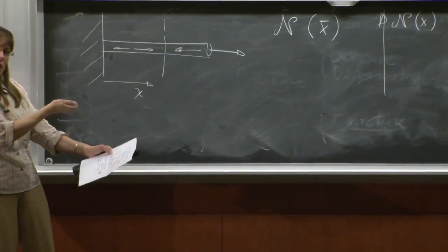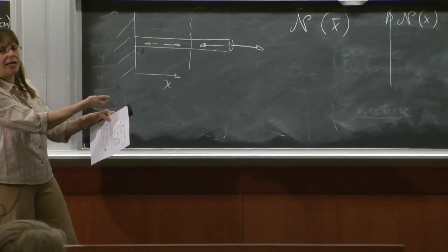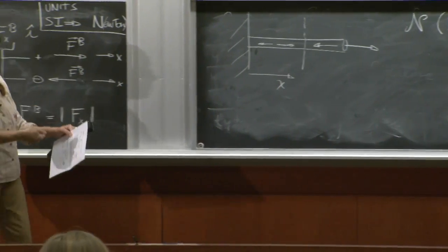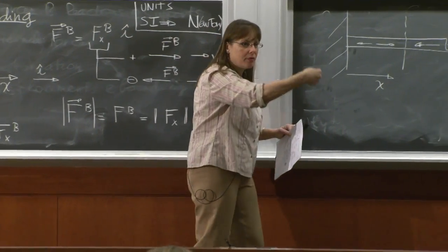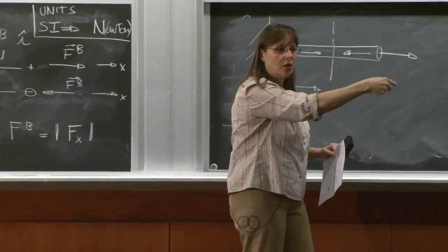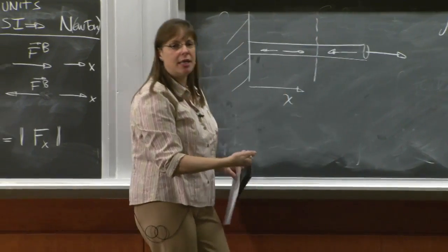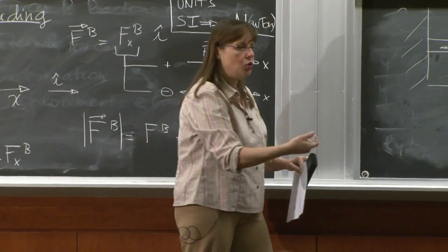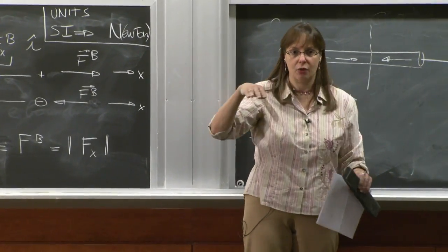Imagine that you're doing tug of rope, and you are one team on this side, and there is the guy up front, and then the guy behind, and everybody's pulling. The axial force in the rope steps up every time there is an extra person. That's why the rope in the middle has a lot of axial force. And then you come in at the end, you pull a little bit, the guy next to you pulls more, pulls more, pulls more, so the axial force can change inside the rope.